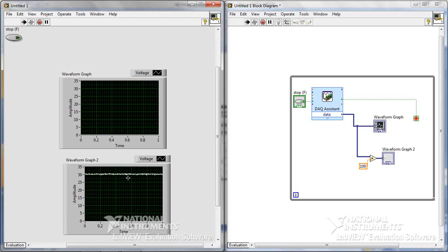you can see the temperature is 29 to 30 degrees. Obviously your output shows a voltage, since I have given it as a voltage. Here you find the same value in terms of millivolts, and obviously you won't be able to see it. Here it is converted to volts. From here to here, that conversion is happening. I'm getting the data in millivolts, so I'm calibrating by multiplying by a factor of 100 and giving it to my waveform graph.